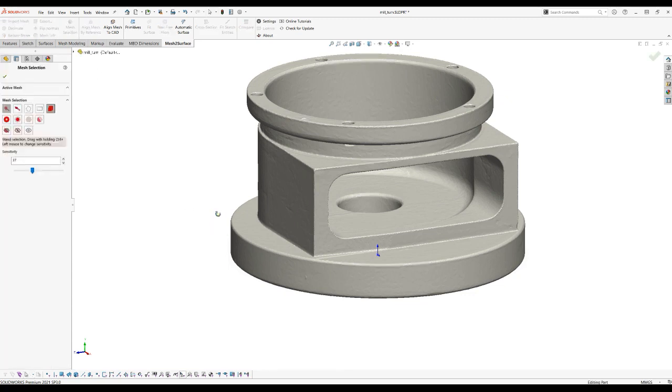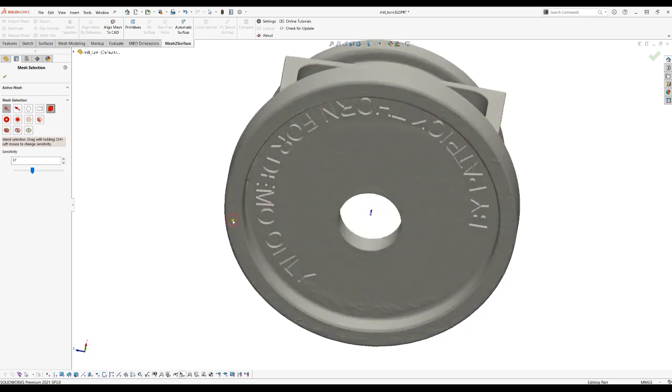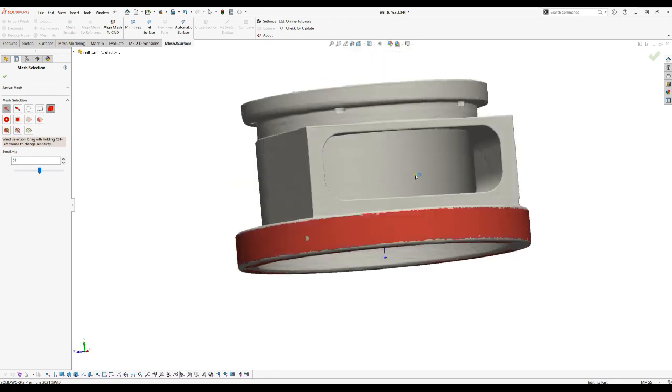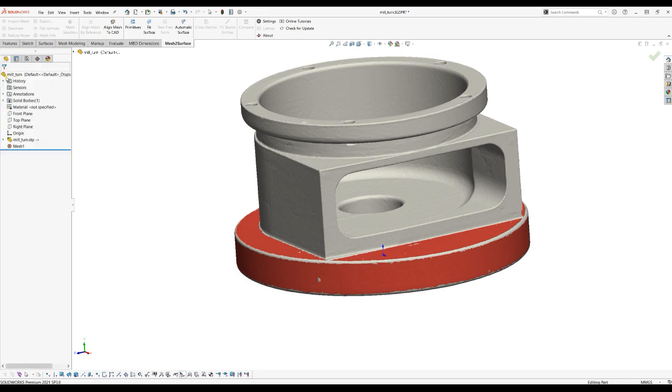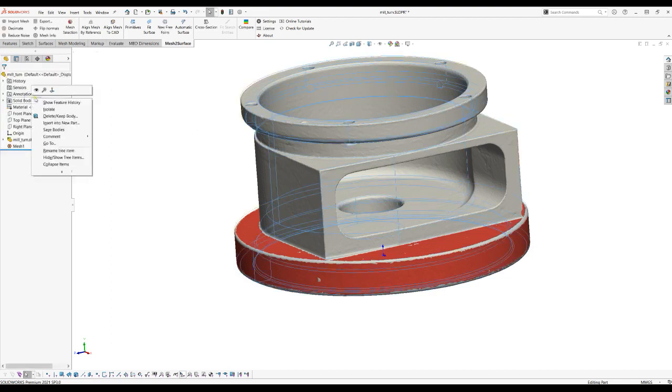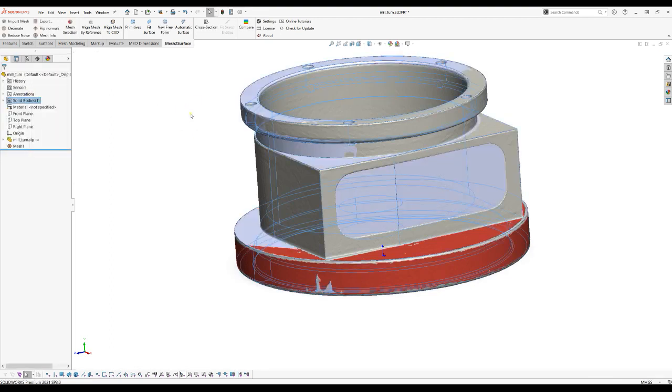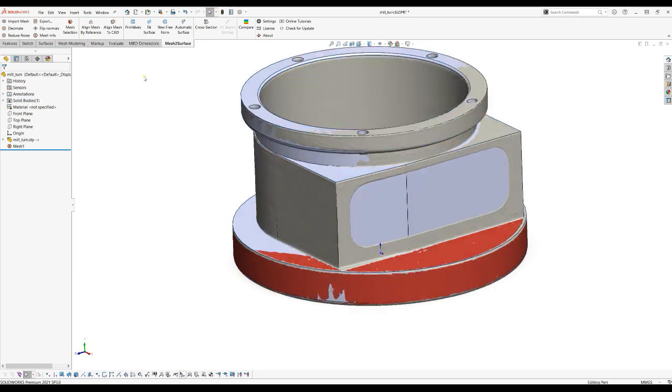What I'll do here is mark with our tools the areas of the surfaces that I trust most. For example, I'm sure that I want this plane to be used. I can use the different selection tools, and I can pick an area here just to get more flat surface, and I can click on this cylinder, for example, or maybe I can pick this area as quite important. When I'm happy with this, I can just press OK. I'll show my CAD model because I need this as a reference for my fine alignment.